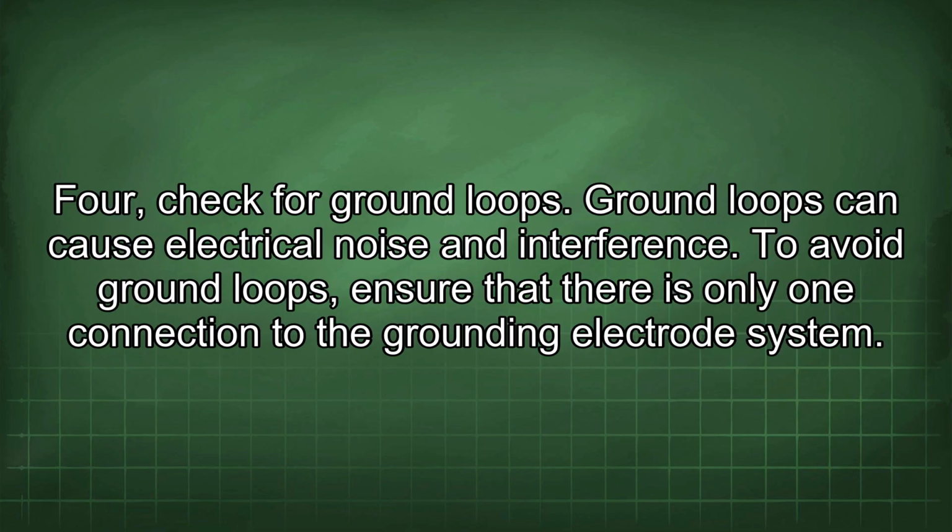4. Check for ground loops. Ground loops can cause electrical noise and interference. To avoid ground loops, ensure that there is only one connection to the grounding electrode system.